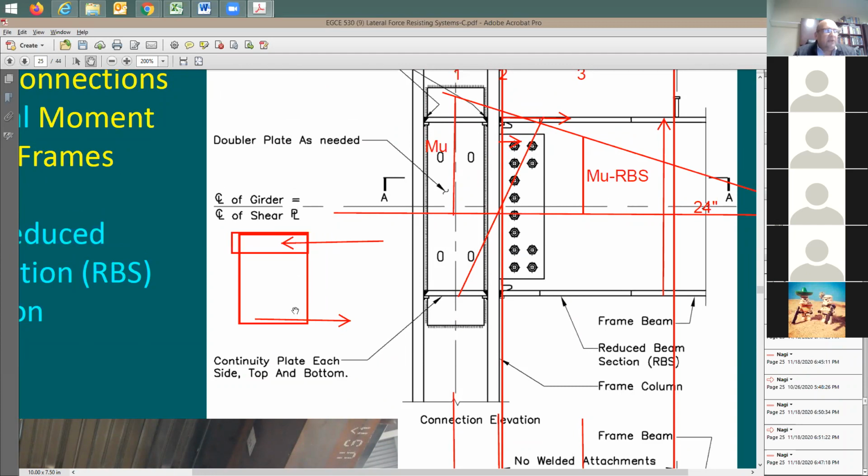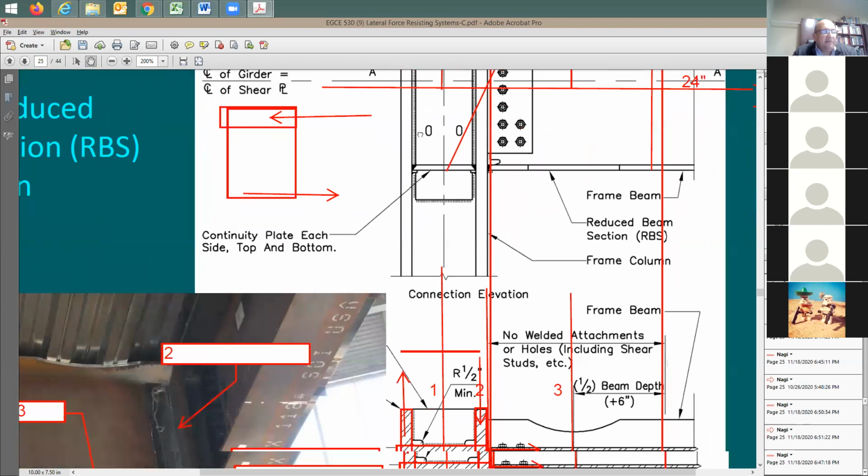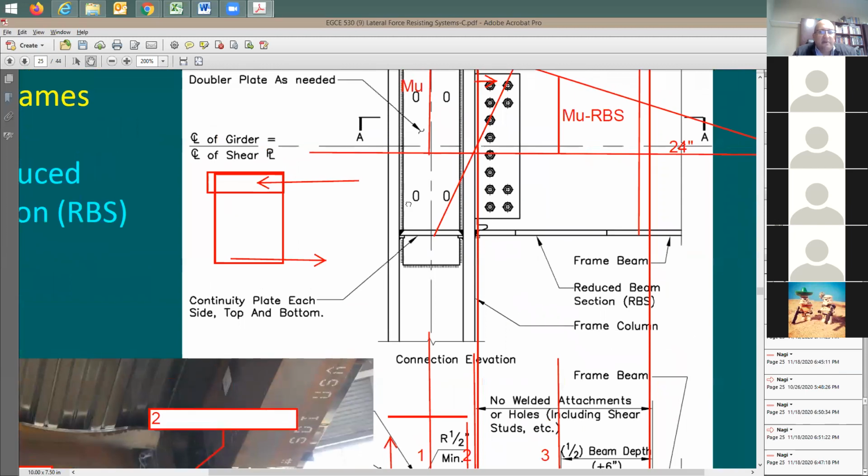Now, where's the tension compression? You're going to say it's going to be in the extremes. How about in the middle? Do you have some transfer for any tension compression? You're going to say, yeah, a little bit, but not much. Same thing here. The web, generally speaking, is going to be very small. It doesn't take lots of moment, if you like. And then these tension forces are caused by seismic mainly.